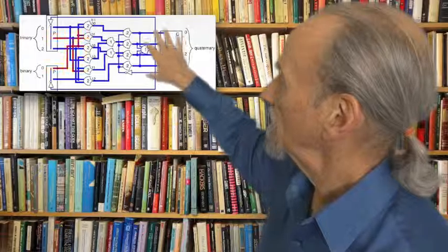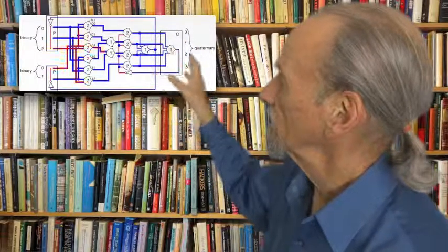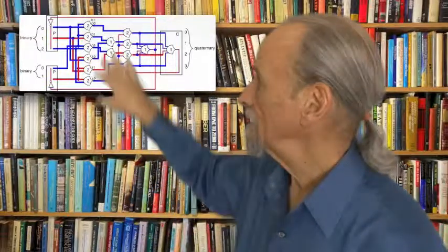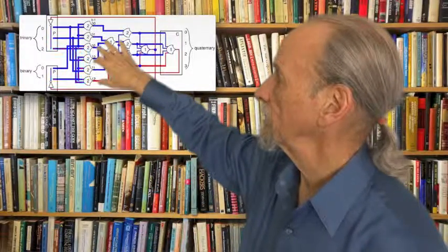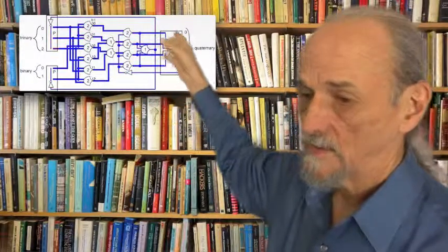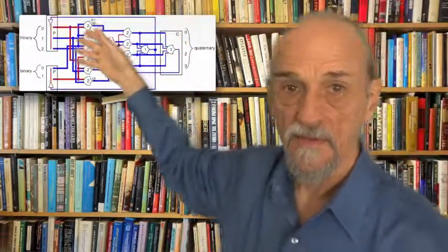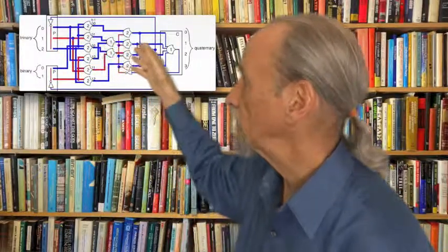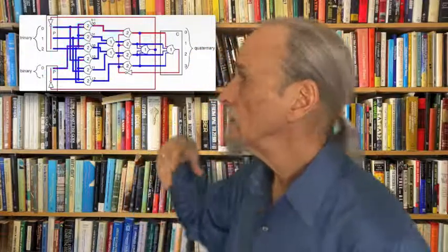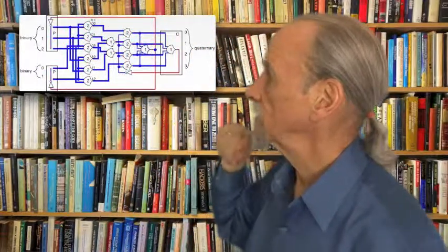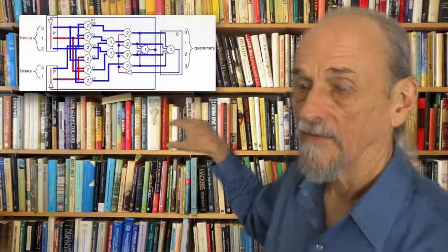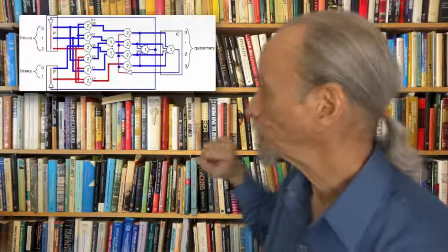And here we have the link, the enable link, and the completeness. And ahead of that we have a combinational circuit. This combinational circuit fulfills the completeness criterion, which means that whenever its output transitions to data, it means that both inputs have transitioned to data. And whenever its output transitions to null, it means that both inputs have transitioned to null. So this circuit fulfills the completeness criterion in the same way that the link circuit fulfilled the completeness criterion.